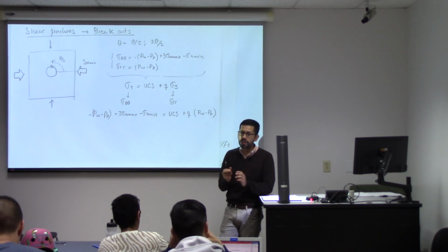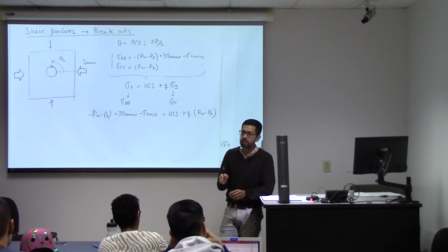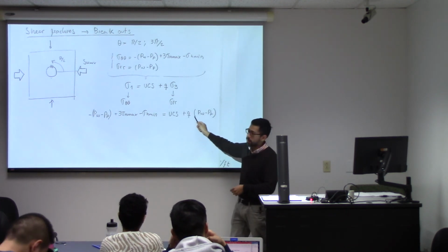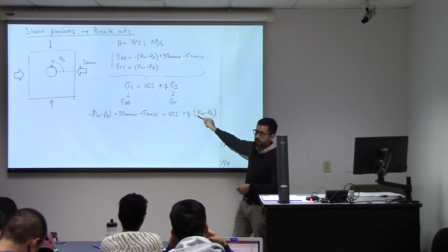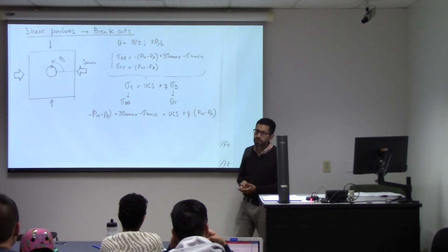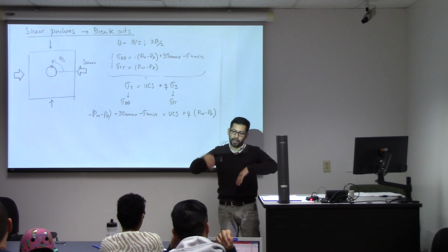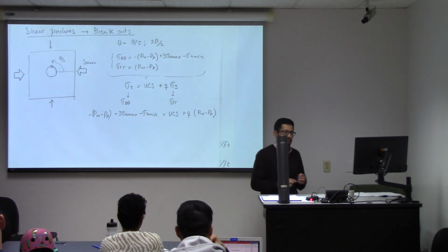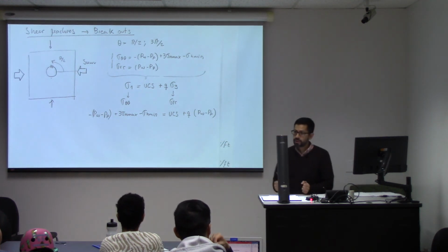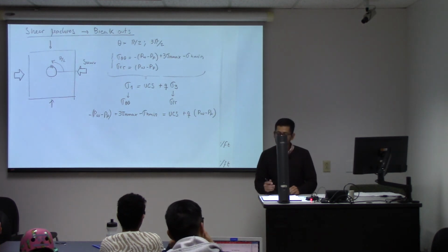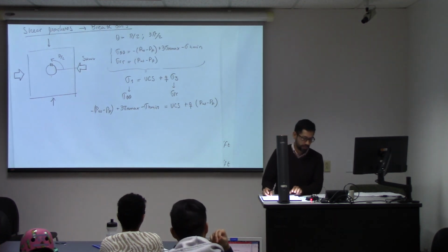With the confining stress, it can become a very strong rock. And this is all due to the mud cake and the difference of pressure between the wellbore and the pore pressure in the rock. That applies support around the wall that allows you to go through a very strong material, even though it's uncemented, because you have an effective stress, still strong.